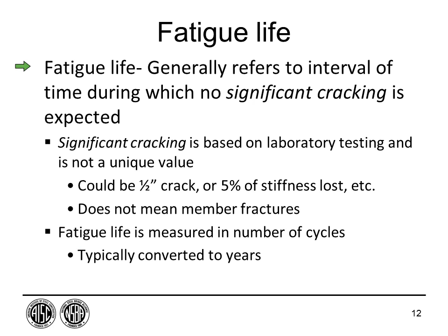The girder failed. So is that when I can first find a tiny crack, or is that when the girder's laying on the ground? Well, generally some criteria are put in place that a crack is a certain length, or I've lost enough material to change stiffness. It doesn't necessarily mean, though, that the member is broken, and that's an important point.